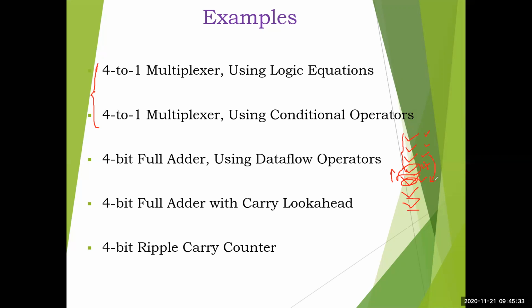And this is possible only because of the logic synthesis tool. I mentioned logic synthesis in the very first module, on the evolution of CAD tools. Because of this logic synthesis tool, we are going to do the design at RTL level. And what is RTL level? It is a combination of data flow and behavioral level.